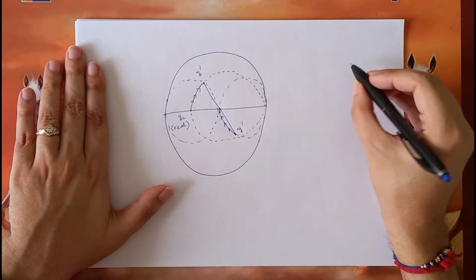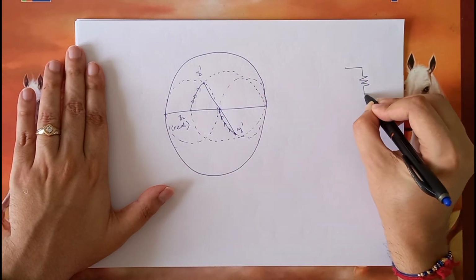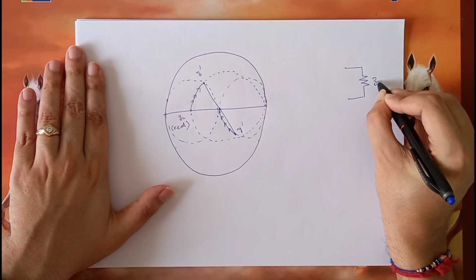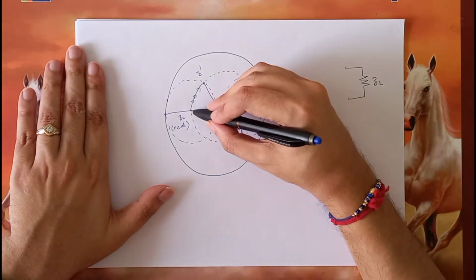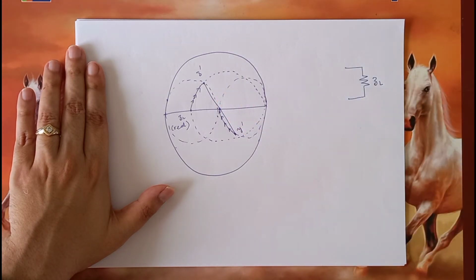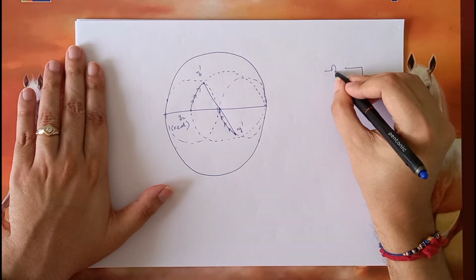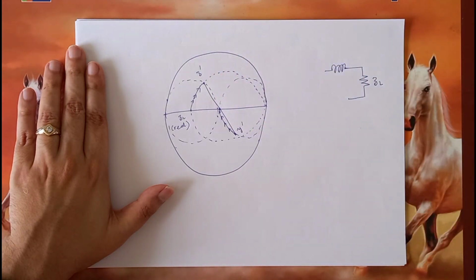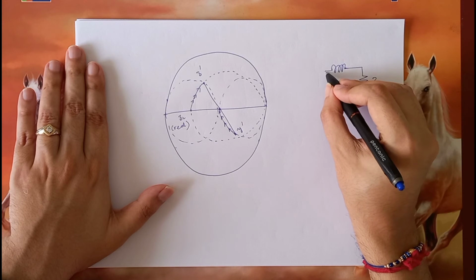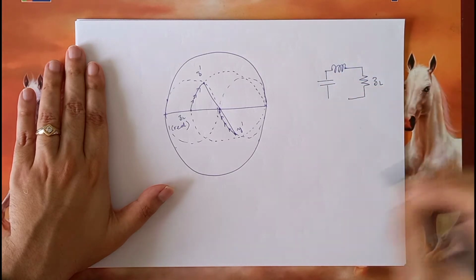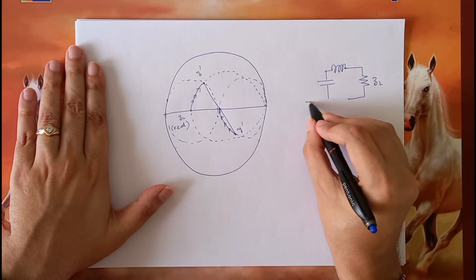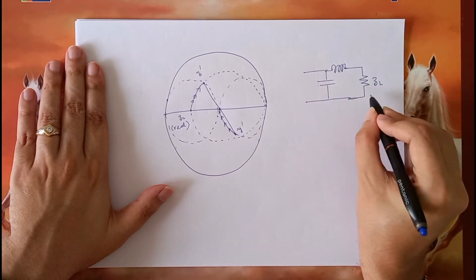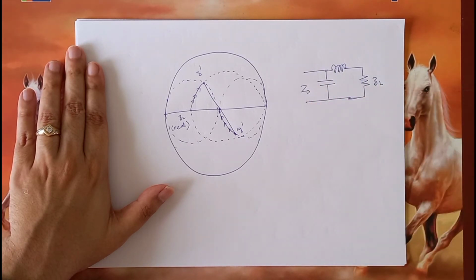So effectively, if the load impedance is real, which means it is nothing but a resistor, then moving upwards on a constant resistance circle first would mean that there is an inductor, and then we are switching over to the admittance coordinates and moving up along the constant conductance circle, which means we are adding susceptance, thereby adding a capacitor. And whatever is the Z0 over here, that remains.